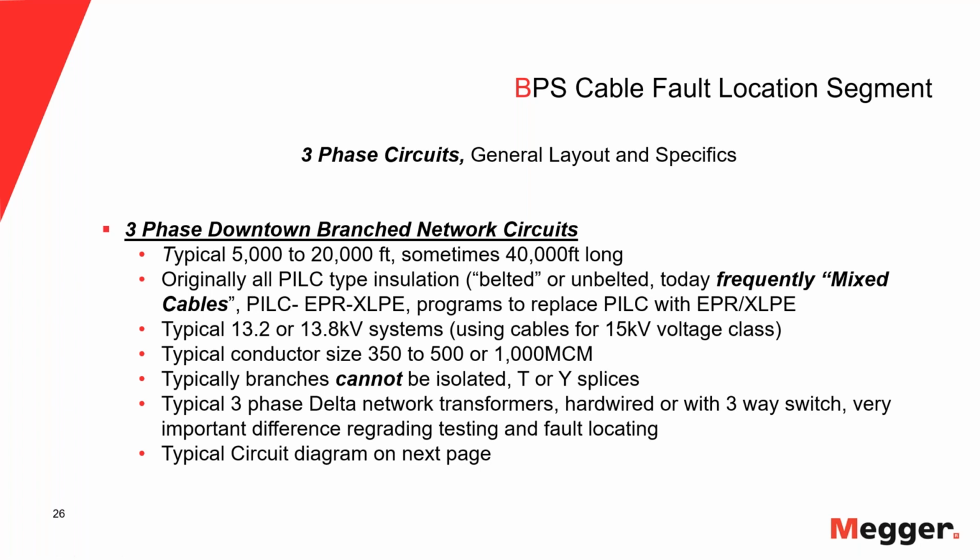Okay, so we have in these systems, like I say, a mix of different type cables, and the voltage is typically only 13.2 or 13.8 kV in these systems, and so pretty much all these cables are 15 kV class cables. The typical conductor size is between 350 and 500. Sometimes you have also 1000 MCM. Again, it depends on the loads.